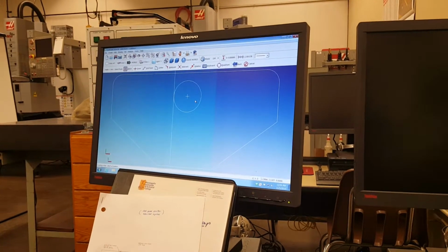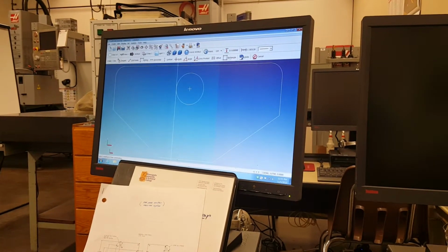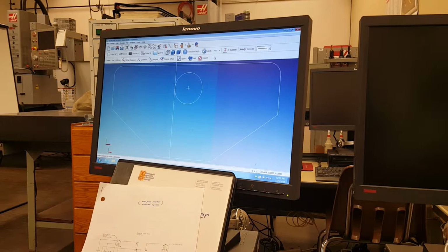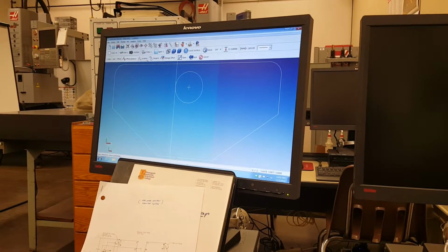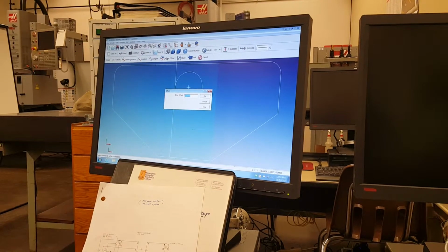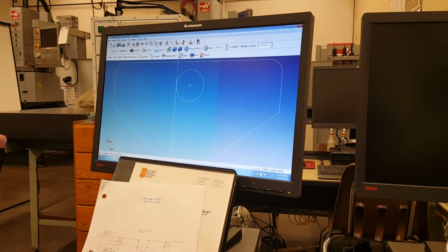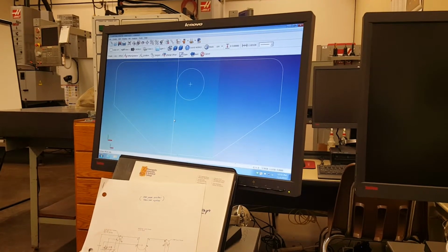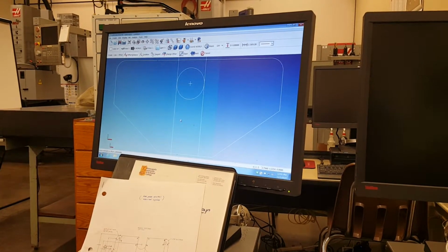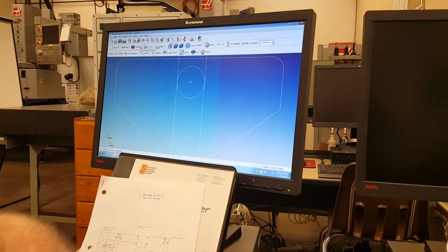Now there's a couple ways I can create the other line, and one is to do an offset line. I can go back, offset line, and change my offset. Instead of 6, we're going to put in 1. Hit OK. And what element? This element. What side? That side. That's one way to do it. I could have done it using keyboard again.